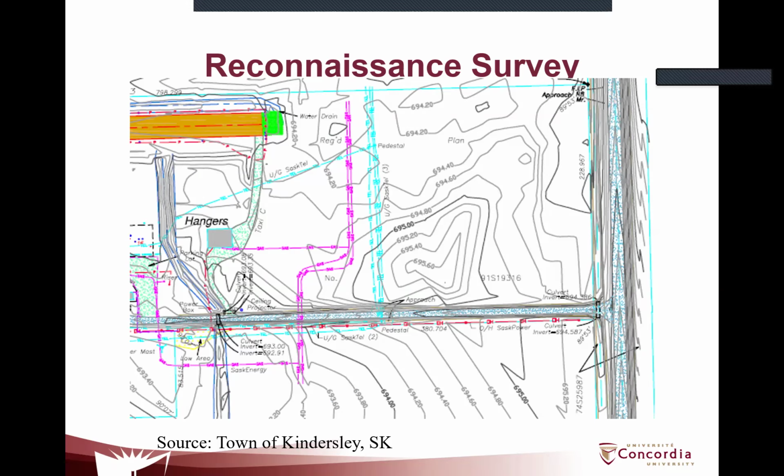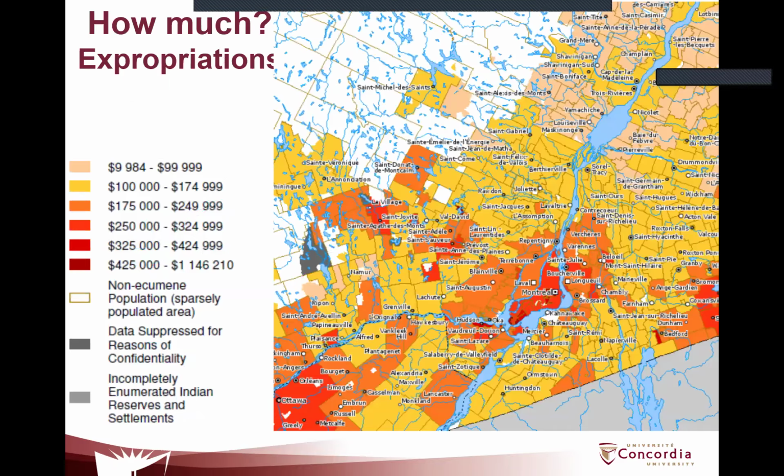So if you are looking into something like this, then you need to either relocate the utilities so that the highway doesn't touch them, or have enough coverage so that you have sufficient separation in terms of depth, so that the load of the vehicles doesn't damage that infrastructure.